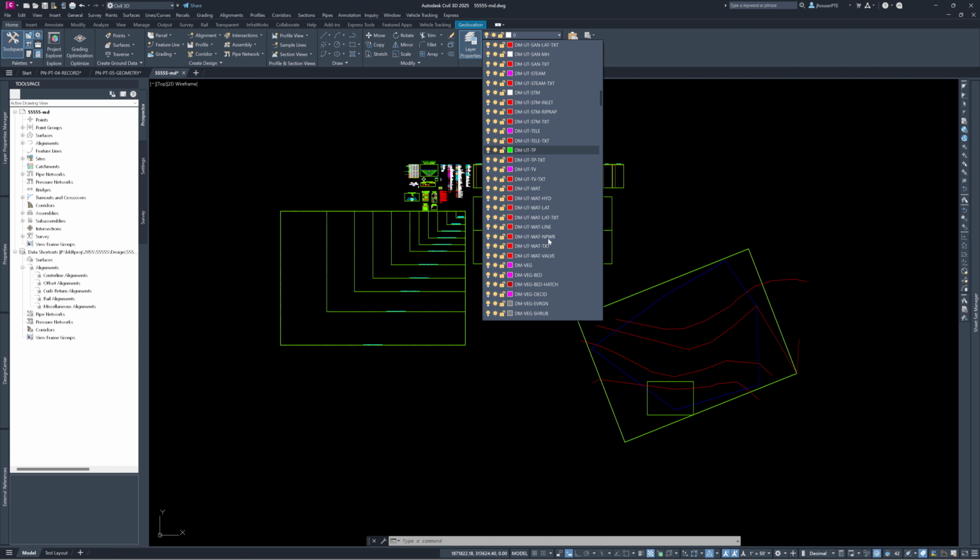Typically, if I'm going to create any kind of surface out of polylines, I now create a no plot layer to put those contours on. That way I can still see those contours, I can edit those contours, but in my final plot out sheet, it's actually referencing the surface display. So I'm going to just put all those right now onto the no plot layer.